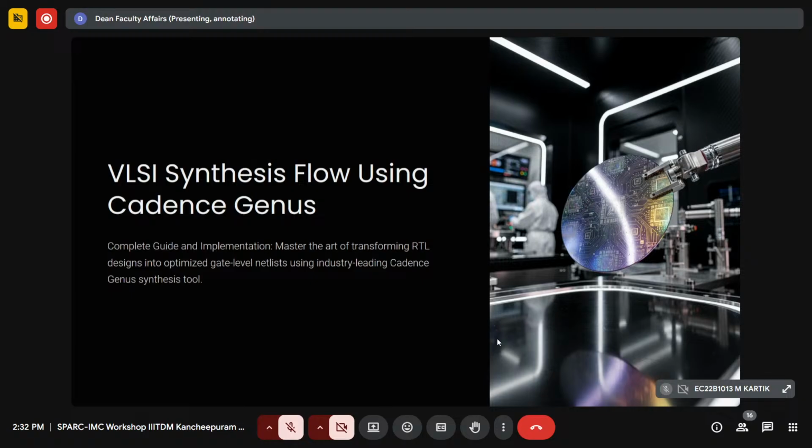So each and every component will have a delay, let's say 30 picoseconds or something like that. So how does it matter for the library, right? Suppose I'm going to take a 22 nanometer process, and the AND gate will have some delay value. It's not a single value. So in the library, they'll have a table format. The table will have input transition and output load, because the AND gate will be there, but the output can be connected to multiple ranges. Similarly, the input can be connected from anywhere else. We don't know how much is coming, so they will also have a range.